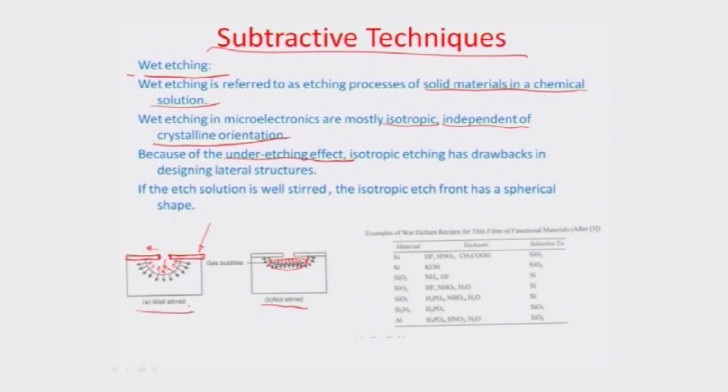Okay. So, these paradigms are used off and on for describing wet etching. What is also important is something called an etch selective layer. For example, you saw this mask here; the mask does not get affected by the etchant itself, although whatever is underneath the mask gets affected. So, this is called an etch selective layer, which is not amenable to the particular etchant which is being used in this context.